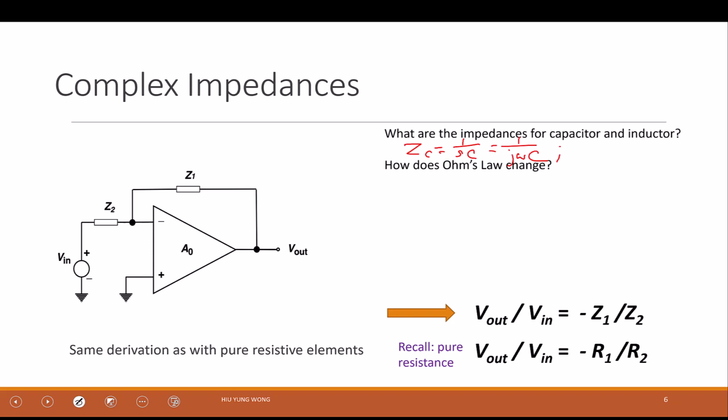Okay, we will discuss a little bit more. Then how about the impedance of the inductor? SL, thank you. Right, so I hope everyone can say this as fast as these few students, right? This is something you really need to know as an electrical engineer. Okay. SL is J omega L, right? We ignore the real part, which is okay. Now, if I write everything in the frequency domain, and actually something very trivial, how about the impedance of a resistor? Just R, right?